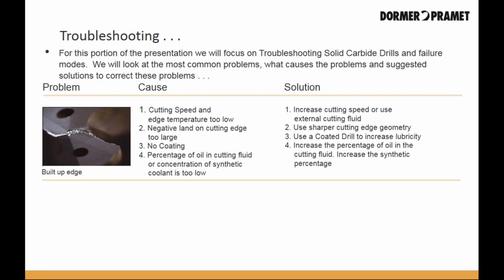Cutting speed and edge temperature is too low. Negative land on the cutting edge is too large. No coating. Percentage of oil in the cutting fluid or concentration of synthetic fluid is too low.